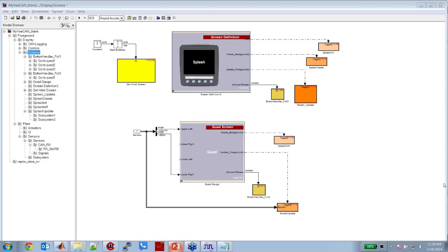So the multi-packet nature would be handled by the transport protocol, and it would provide you the full content of the DM1 message, including the packaging of it if there were multiple frames. But parsing it, it's not presently an automatic feature.